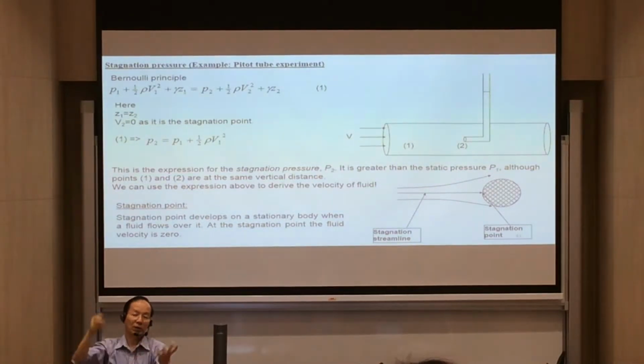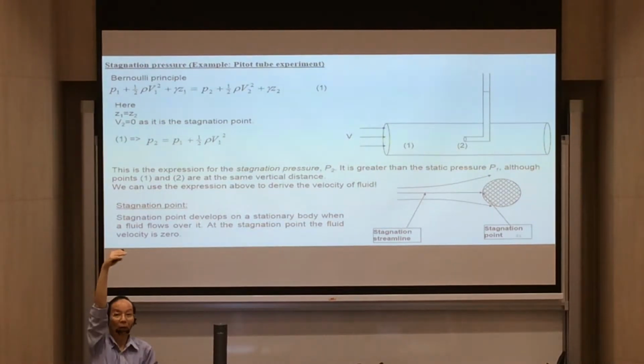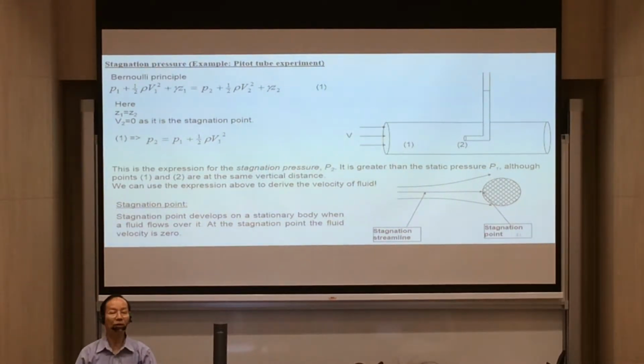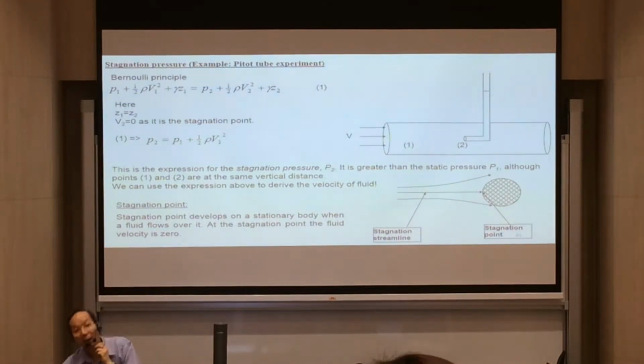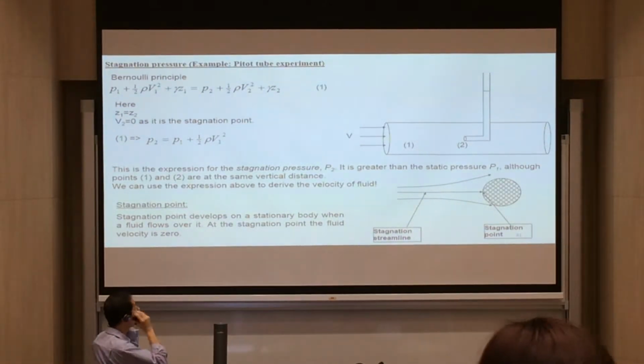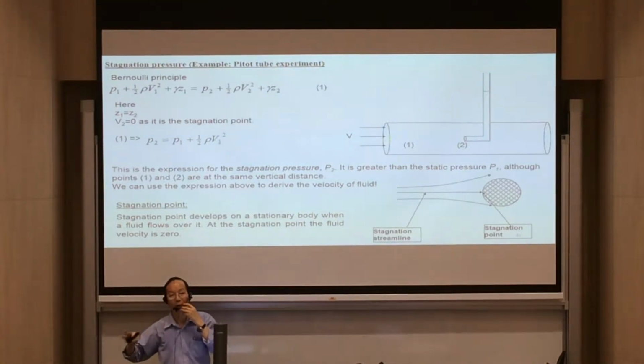In practice, you have a header tank, the water is pumped to the header tank, and then it leads to all the households. But there are situations where it is pumped straight to your piping, to your tap. So again, in that case, this will be modified to take into account the pump, or the turbine. So this is the fundamental basic expression: free flow, no prime mover, no pump, no turbine yet.